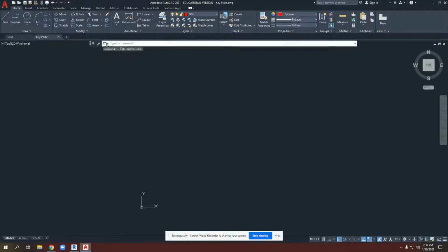All right, back to drawing our lines, and I'm going to just start somewhere in the middle of our screen. And here is ortho, and if I turn ortho off with the F8 key, you'll see that I have any number of degrees of 360 around a circle, whereas if I limit it with ortho, we are kind of stuck with horizontal and vertical lines. So I believe my memory is working correctly. We have a 7-inch line horizontal.